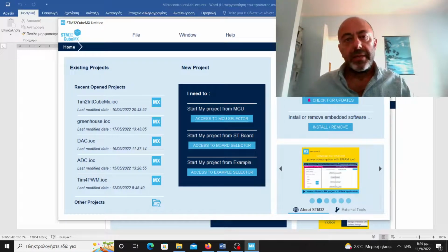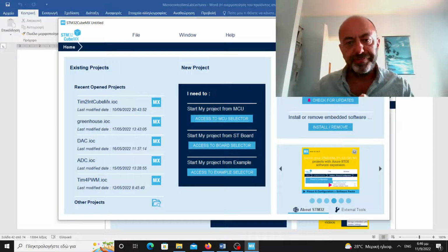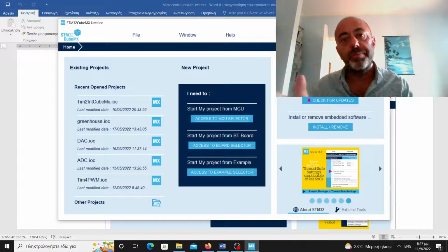Hi, in this video we're going to talk about the output compare operation of a timer, and especially of the timer TIM4, which is appropriate for this purpose. So let me tell you some words about what is output compare. Output compare is the scheduling of an event on a specific output pin after a number of pulses.